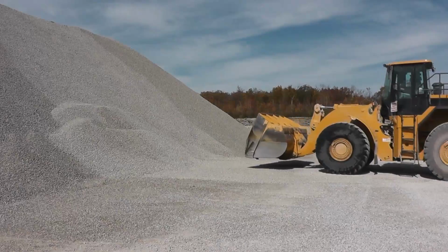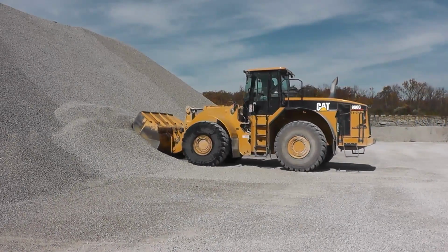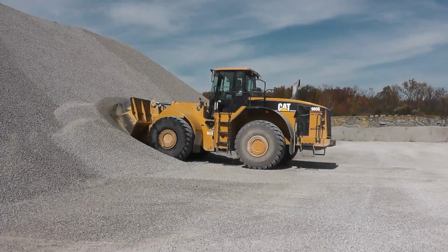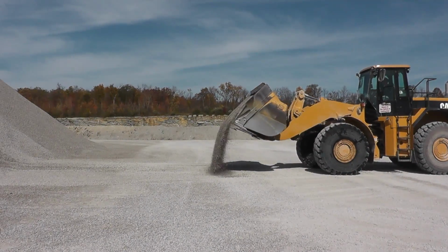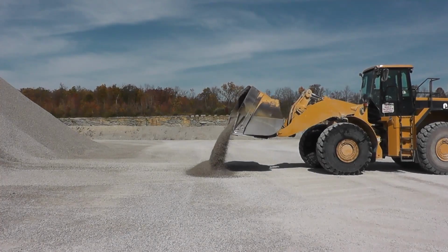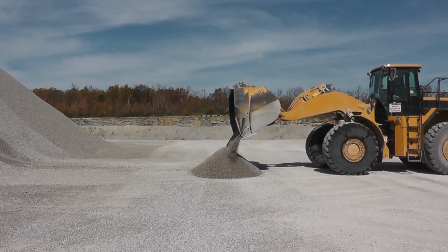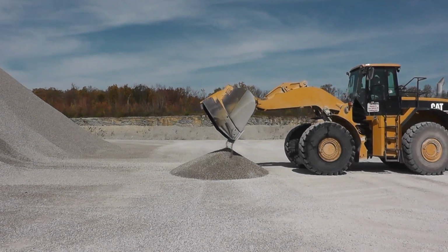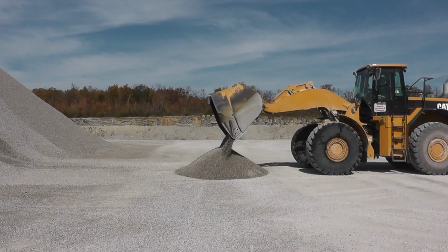The loader operator should not drag the bucket on the existing ground when doing this process because of possible contamination of the stockpile. However, when the material is emptied onto the ground to make the sample pile, the bucket should be as low to the ground as possible, and then the material rolled by slowly raising the bucket at the same time as the bucket is being emptied. The intent here is to reduce the distance the material is allowed to free fall, which will reduce the amount of segregation that may occur.